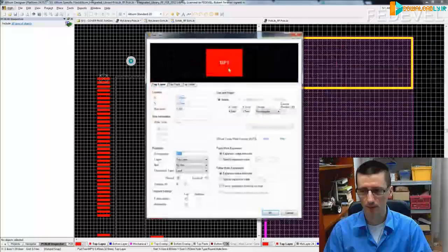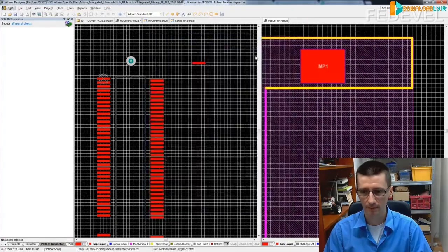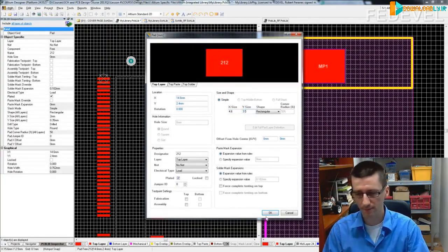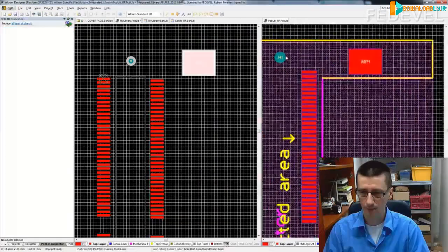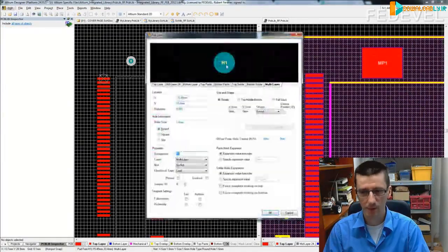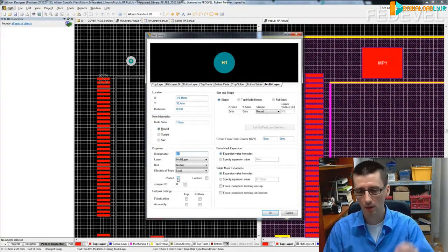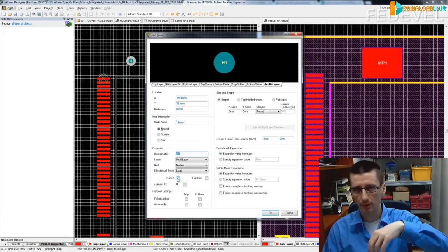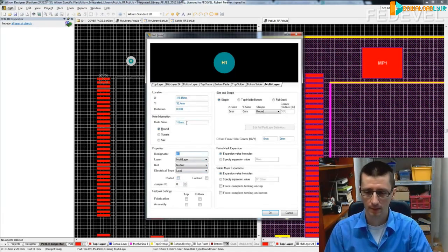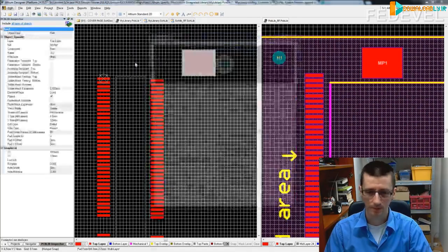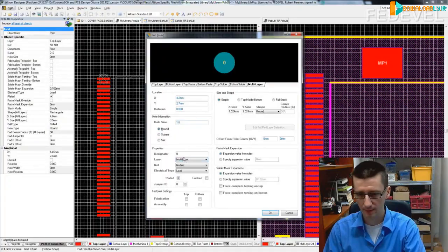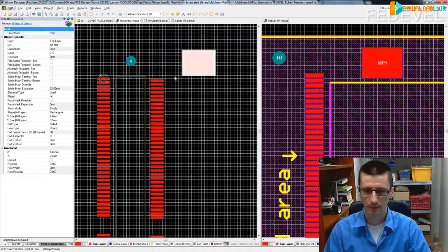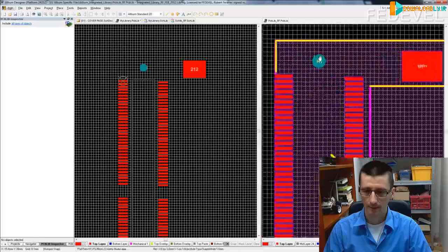From the datasheet you will see what the dimensions are. So 4.6, 3.5, 4.6, 3.5 for the hole. This is actually a special hole because it is not plated. Not plated means that there is no copper in the hole, so there is no connection between top and bottom layer. 1.6 millimeter. 1.6, not plated. There is no ring around the hole.